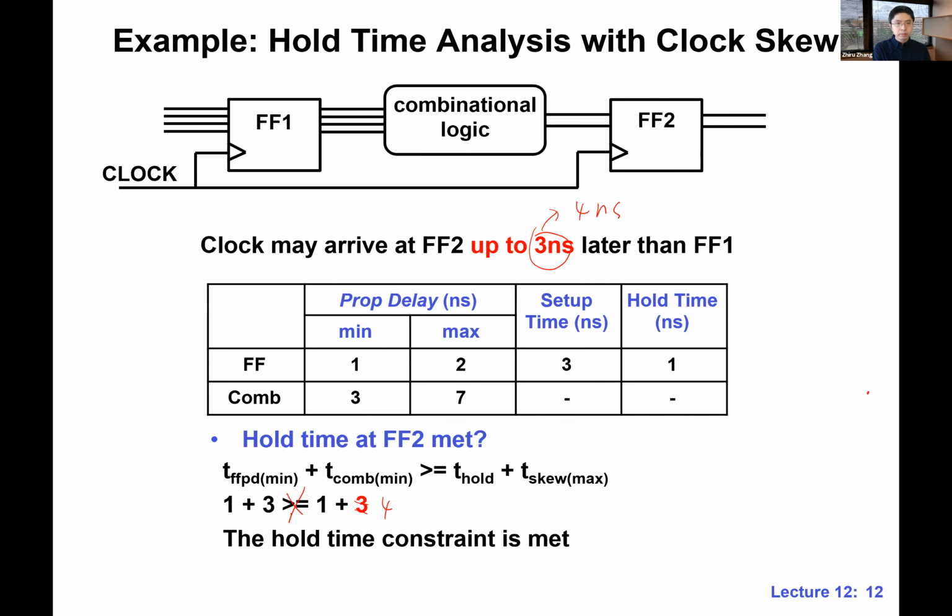Okay, any more questions about timing analysis? Just to repeat, it's really about one thing: to analyze the effective setup time and hold time. In this class, I really want to encourage you guys not to memorize things, like whether positive is harmful or negative is harmful, whether it's for setup time or hold time. Let's try not to do that. Let's try to understand the intuition. And here's the intuition: whether it's harmful or beneficial is really about whether the effective setup time or hold time window is larger or smaller.